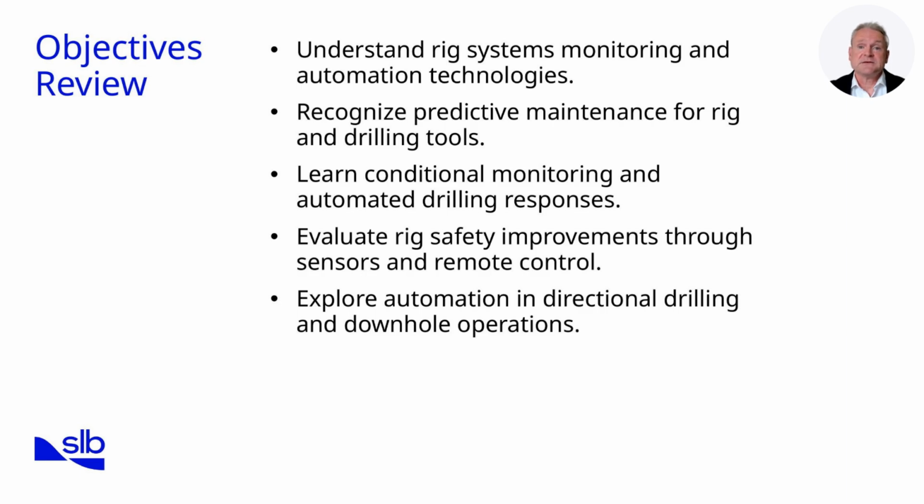Let's review the objectives we set at the start. First, we aim to understand rig systems, monitoring and automation technologies. We covered how networks capture and process thousands of data points, enabling predictive analysis. Second, we wanted to recognise predictive maintenance for rigs and tools. We explored how data on rotation hours, ton miles, and wear sensors forecast failures before they happen.